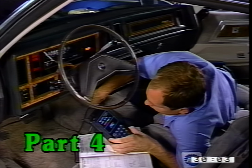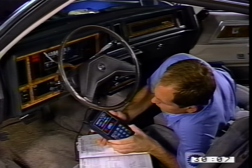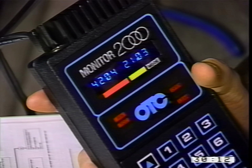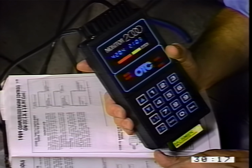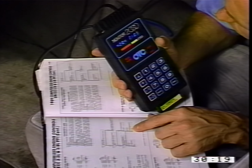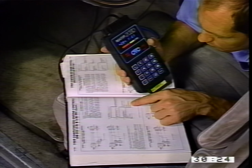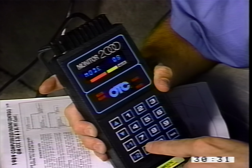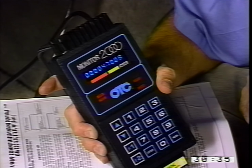Now, let's take a look at a specific trouble code and some related circuit tests, which will give us an overview of what it means to go through a trouble code's decision tree. This engine has given us a code 21. This indicates a TPS circuit problem. Using the GM diagnostic chart and following the outlined decision tree, we can quickly zero in on the specific component that requires service steps. Using a scan tool, we'll determine if the voltage is over 2.5 volts with the throttle closed.